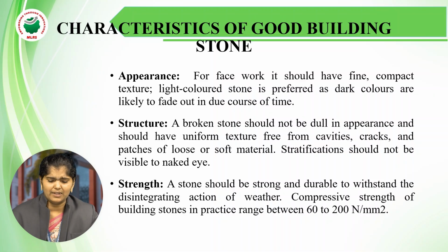And next, characteristics of good building stones. What are the characteristics of a good building stone? It should have good appearance, structure and strength. First, we discuss appearance. Appearance is for face work; it should have a fine compact texture and be light colored. Light stone is preferred as dark colors are likely to fade out in the course of time.